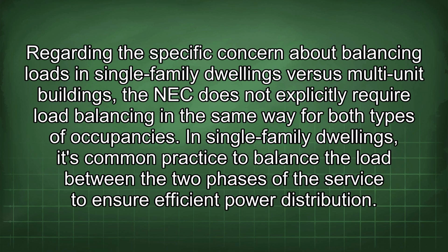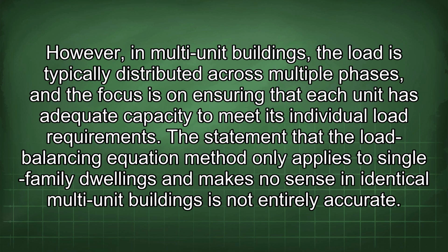Regarding the specific concern about balancing loads in single-family dwellings versus multi-unit buildings, the NEC does not explicitly require load balancing in the same way for both types of occupancies. In single-family dwellings, it's common practice to balance the load between the two phases of the service to ensure efficient power distribution. However, in multi-unit buildings, the load is typically distributed across multiple phases, and the focus is on ensuring that each unit has adequate capacity to meet its individual load requirements.